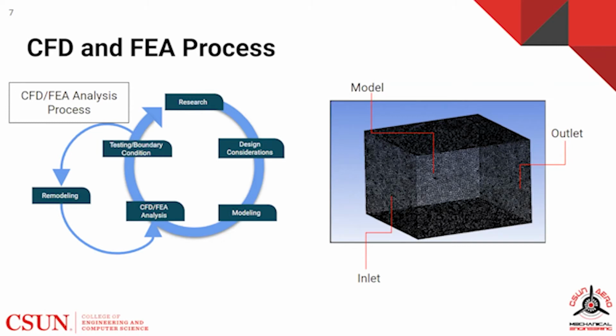On the right, you can see an example of the CFD boundary conditions that were used to model different components. We had the model centered around a big mesh area that is used to mimic real life where the air is free to flow. The flow comes from the inlet and out from the outlet, as shown inside the figure.